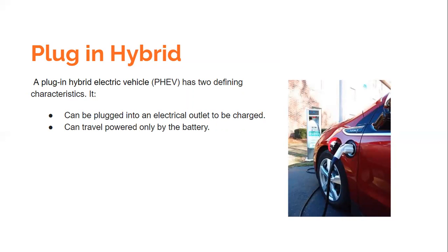It uses both an IC engine and an electric powertrain like an HEV, but the difference, as I said, between them is PHEV uses electric propulsion as the main driving force. So these vehicles obviously require a bigger battery capacity as compared to hybrid electric vehicles, as compared to HEVs.